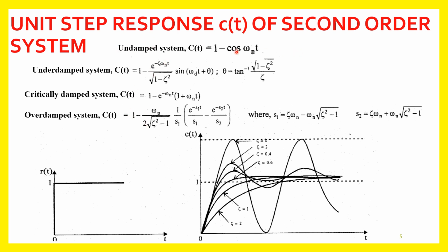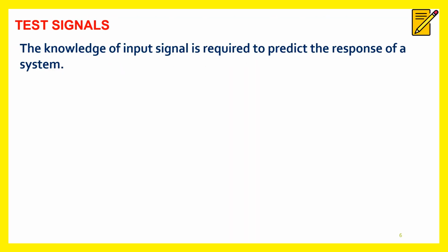For the undamped system, it never settles and is full of oscillations, and the maximum magnitude it takes is 2. But the target value is only 1 and the final value is 2. So we will not use an undamped system. Most practical systems go with underdamped systems.